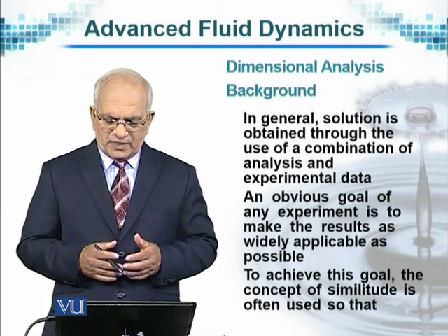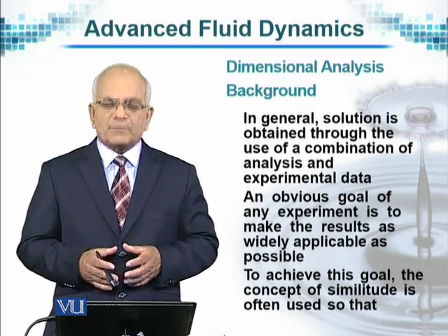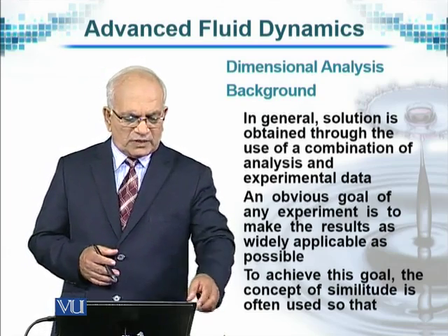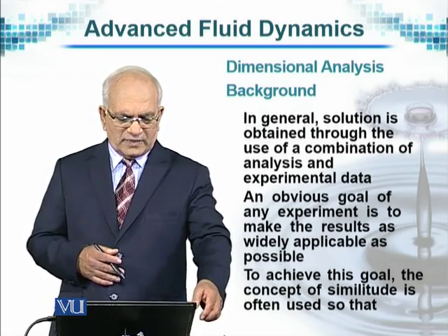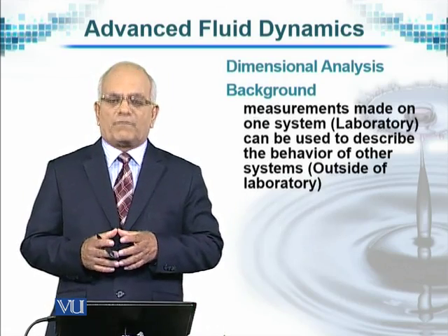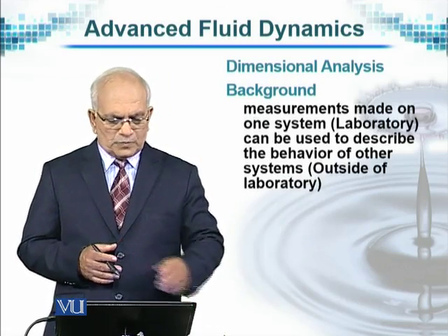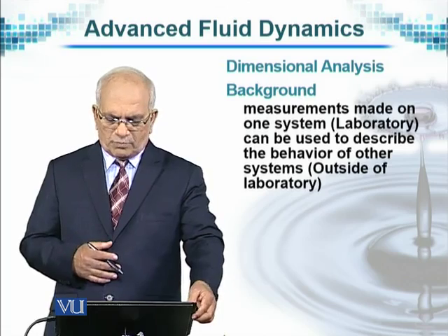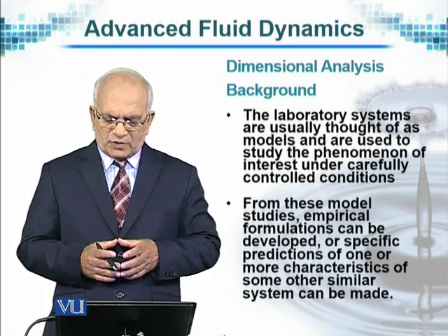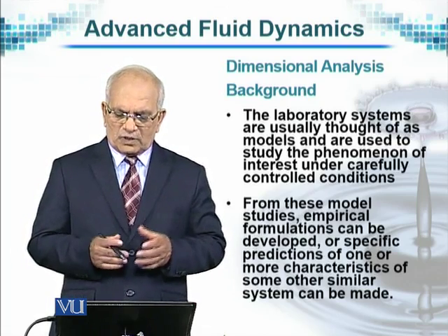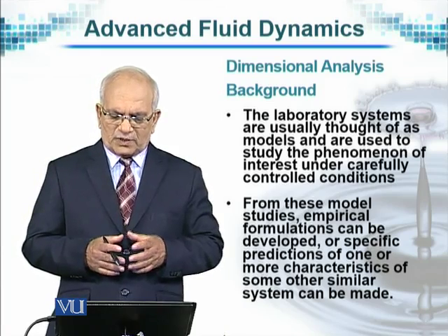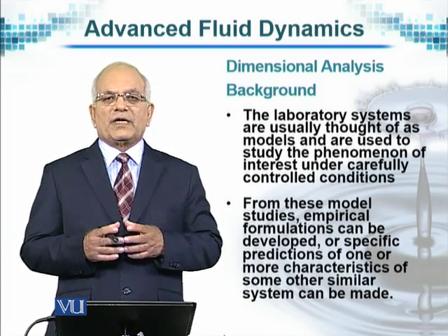But how to do it is a problem, and that problem has been met by using the similarity or similitude technique, using dimensions of the fluid flow constraints. The laboratory systems are usually thought of as models and are used to study the phenomena of interest under carefully controlled conditions.